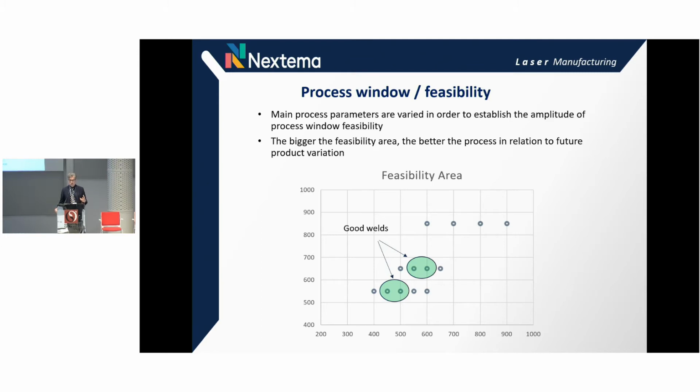For example, you know that a classical metal sheet is going to have variation in thickness of about 20% normally. You will have variation in the elastic modulus of the materials. You will even have changes in chemical composition.